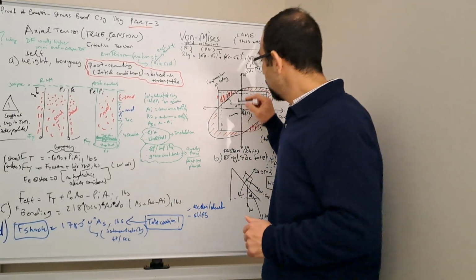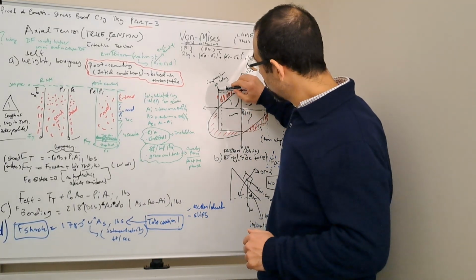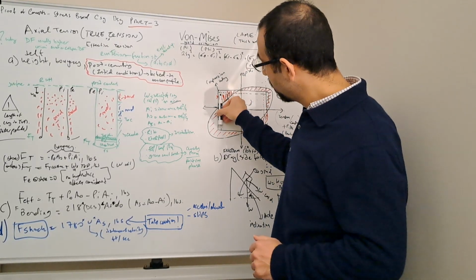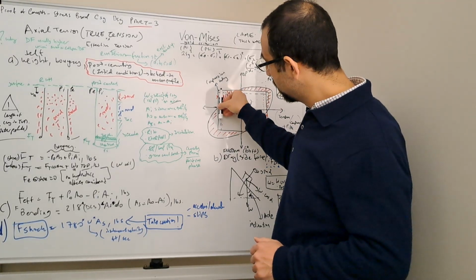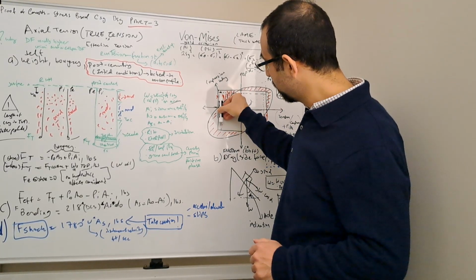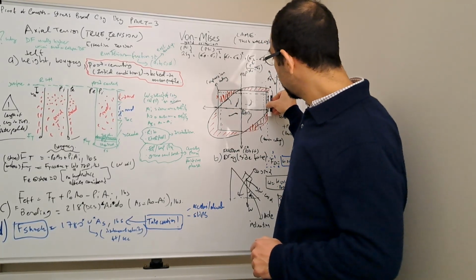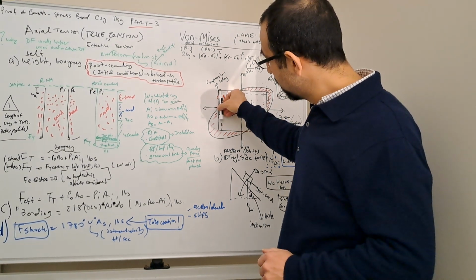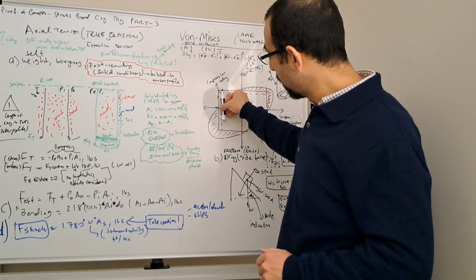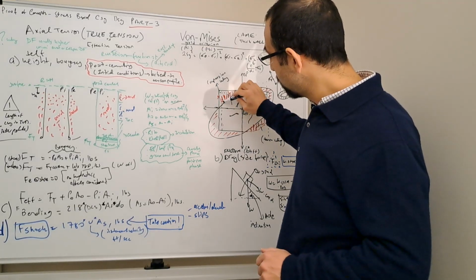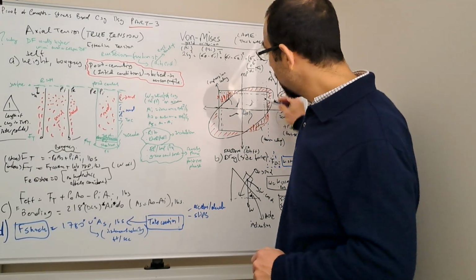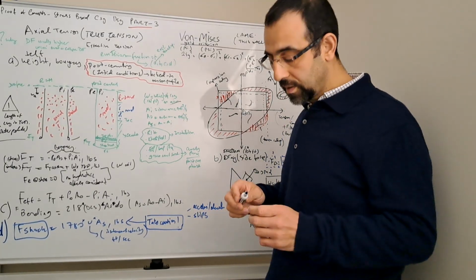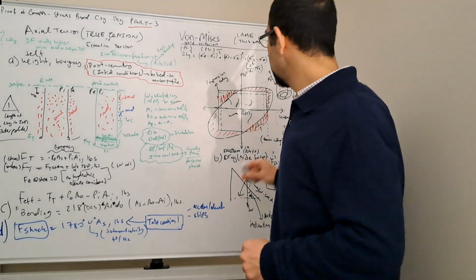Okay, and here you have the compression line and you have the tension line. Those are the performance ratings of the pipe. Also here you have the compression rating of the pipe, and here you have the tension rating of the pipe, and you have the design factor. If you increase the design factor, what happens is the line will come closer to the dash line, and the same happens here. So the effective area where the casing is acceptable effectively reduces.